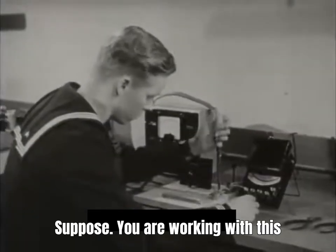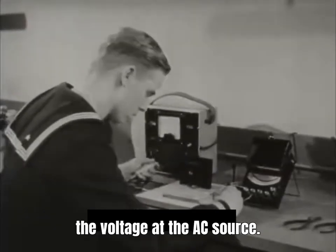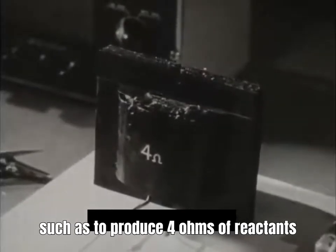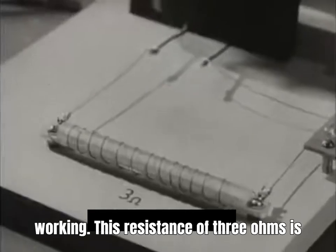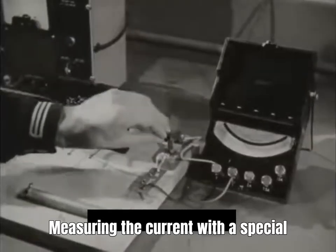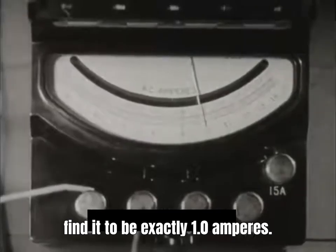Suppose you are working with this circuit and that you wish to calculate the voltage at the AC source. This coil, which is wound with heavy copper wire, has an inductance quality such as to produce 4 ohms of reactance at the AC frequency with which you are working. This resistance of 3 ohms is connected in series with it. Measuring the current with a special ammeter which reads maximum values, you find it to be exactly 1.0 amperes.